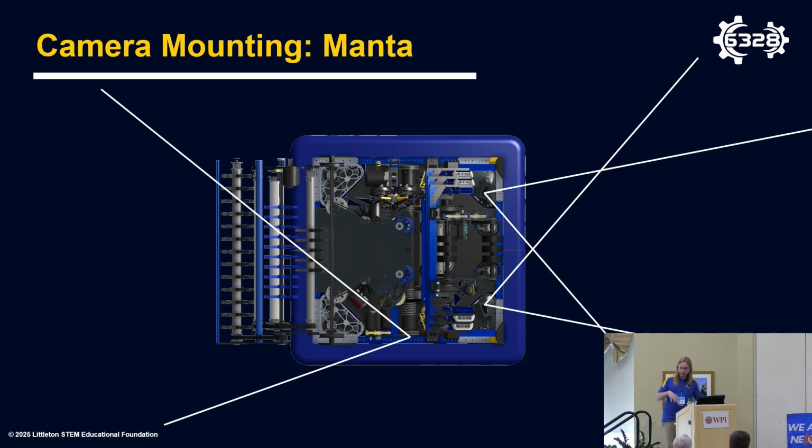Now, in the back of the robot, we also had a camera. There were two variations of this robot. When we were picking up coral with a hopper, we were using that back camera for alignment to the tag on the human player station, so it was angled up quite a lot to support that. And with the ground intake, the latest iteration, we angled it down and switched it to a color camera for game piece localization. So we're switching it based on the exact needs of what we need the vision system to support.